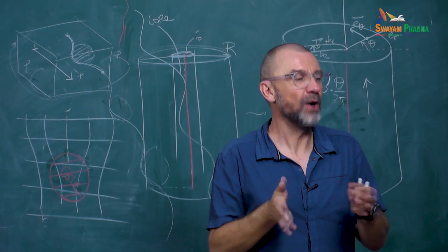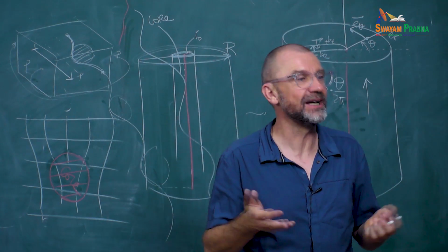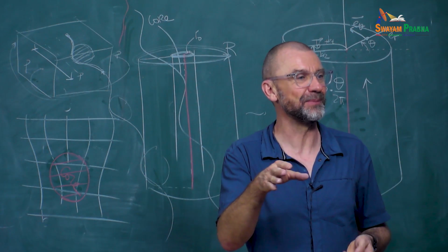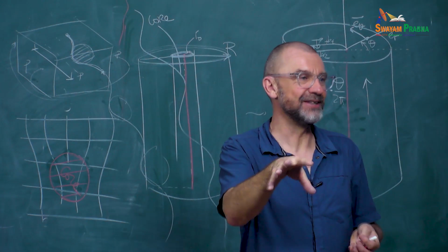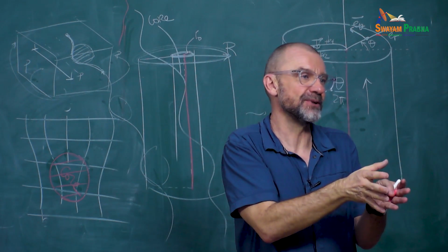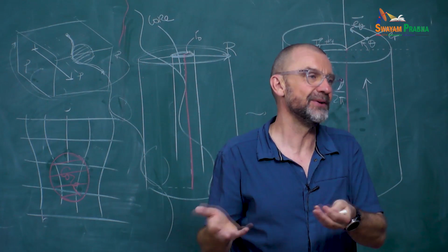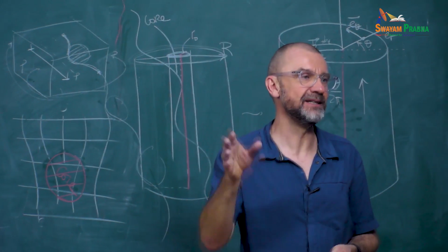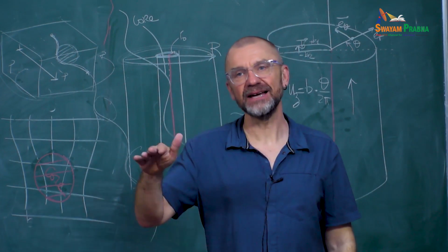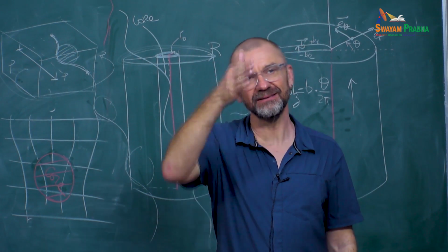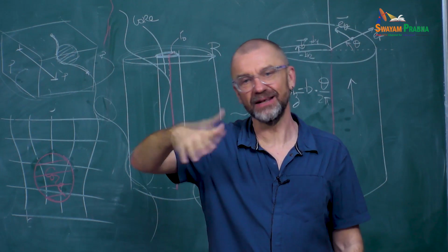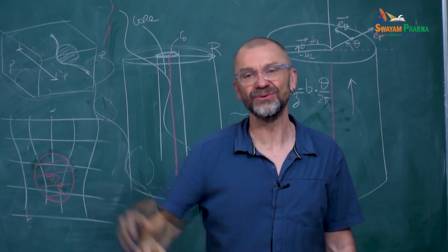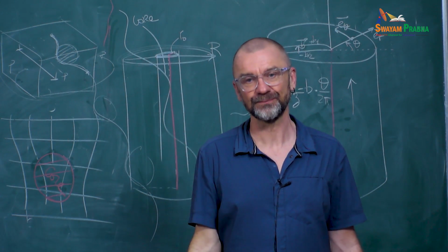With MD, we will always be limited to one, maybe two dislocations at most, whereas with DD, you can go to much larger. It's the same as when you go from DFT to interatomic potentials. You can fit such that the interatomic potential will reproduce exactly the DFT on small cells. Then you can do bigger cells, but you know that it's not going to be as accurate as the initial DFT. So it's the same philosophy between MD and DD. When you look at this size effect on the yield stress, you can see that it converges, and then you can either say, I'm sufficiently converged, or you can do an extrapolation and try to do a prediction.